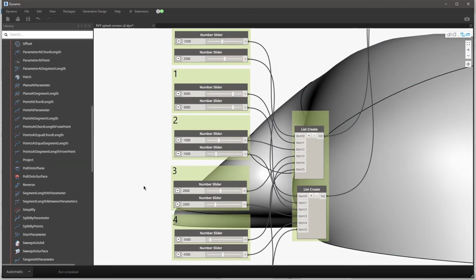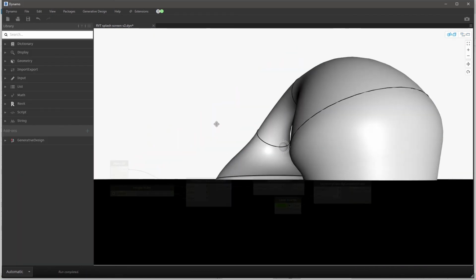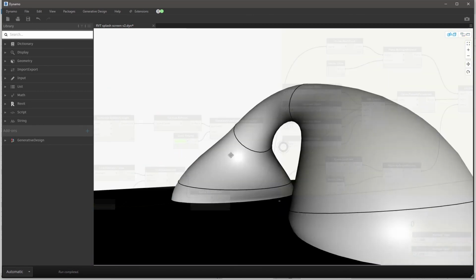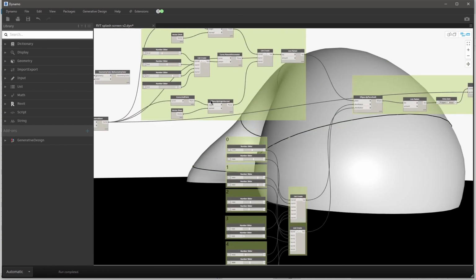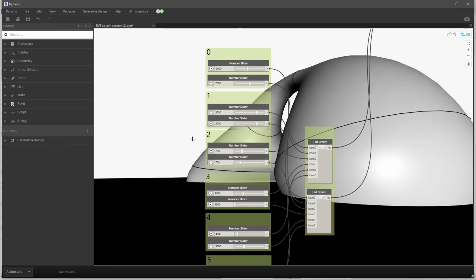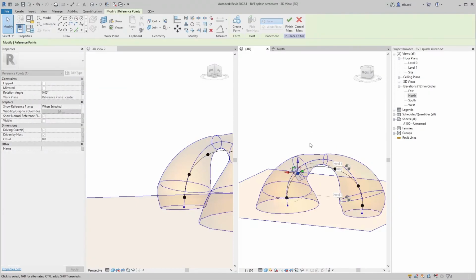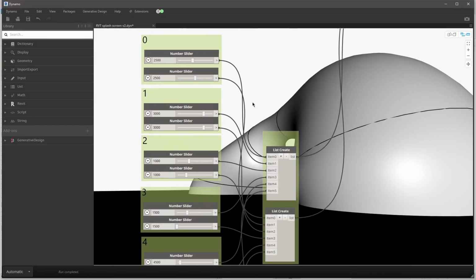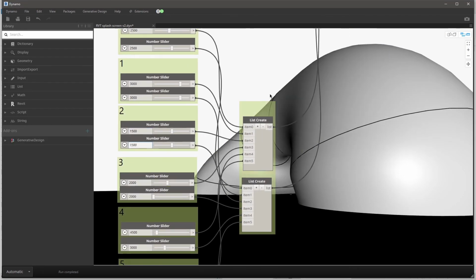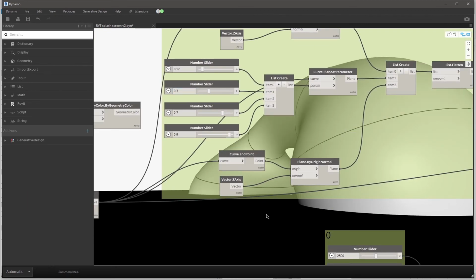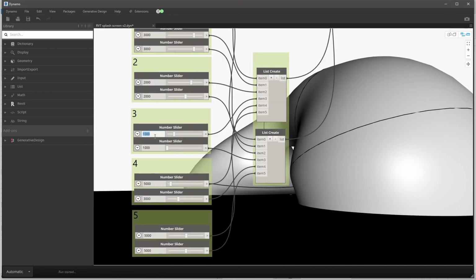And as I played around with those ellipses, I figured out that I have to add a surface for the ground and push the start and the end of the lead curve below the surface, so that the main surface starts and ends below the ground level. In that way I can get closer to the right shape that is made in the Revit splash screen. And also in the splash screen you can see that the main structure starts and probably ends below the ground. It's also kind of apparent in the Revit splash screen that the structure begins and ends below the ground level.